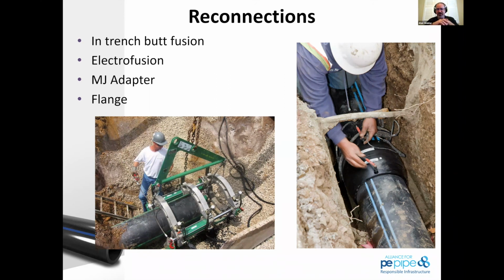We had a question earlier on, Matt, and I want to talk about it a little bit now, which is the largest size of pipe bursting that has been conducted to date. I was working a pipe rehabilitation project for very large cast iron and chased down this rabbit hole. The largest that I had been aware of by my discussion with lots of industry reps was about 48 inches to be able to be burst. But the equipment and tooling that is now being developed can get up to about 54 inches.